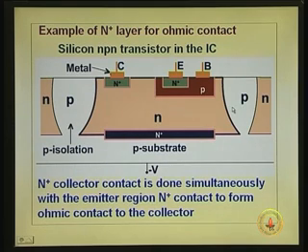be sufficient. Now, notice here, this P layer is connected to this P substrate, and that is connected to minus, so that the P n junction is always reverse biased. So, in the IC, the most negative point, the substrate is connected to the most negative point. So, now coming back to this device. In this region, this island is the region where you form your transistor. That is where you form your transistor.